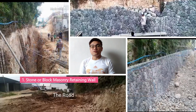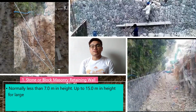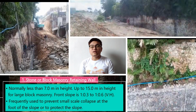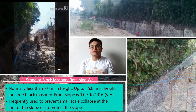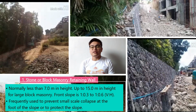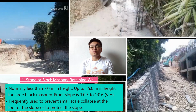Number 1, stone or block masonry retaining wall. For large block masonry retaining wall, normally the height is less than 7 meters up to 15 meters. The front slope is at a ratio of 1 to 0.3 up to 1 to 0.6 vertical height. Frequently, these stone or block masonry retaining walls are used to prevent small scale collapse and also to protect the